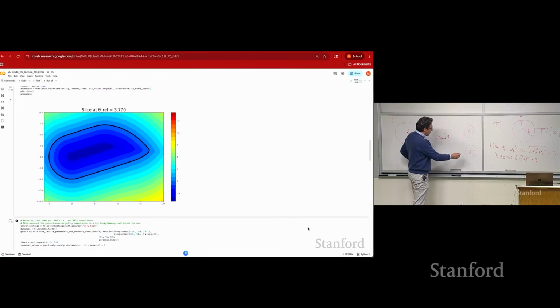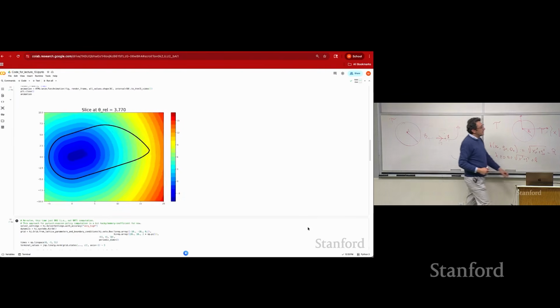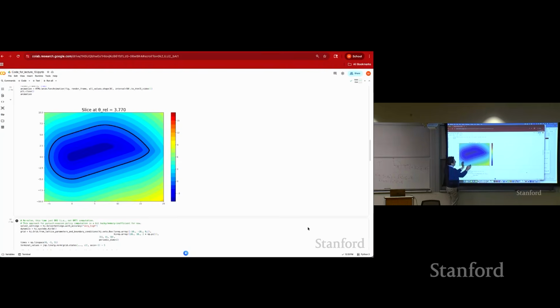Of course, because this guy, in order to really collide with us, needs to do a much more complicated maneuver, and we have much more space to evade. So that's why the reachable set is tilted. It's simply saying that if you start with a negative lateral distance, you need less buffer. With a positive distance, you need more buffer, up to 5, say, meters.